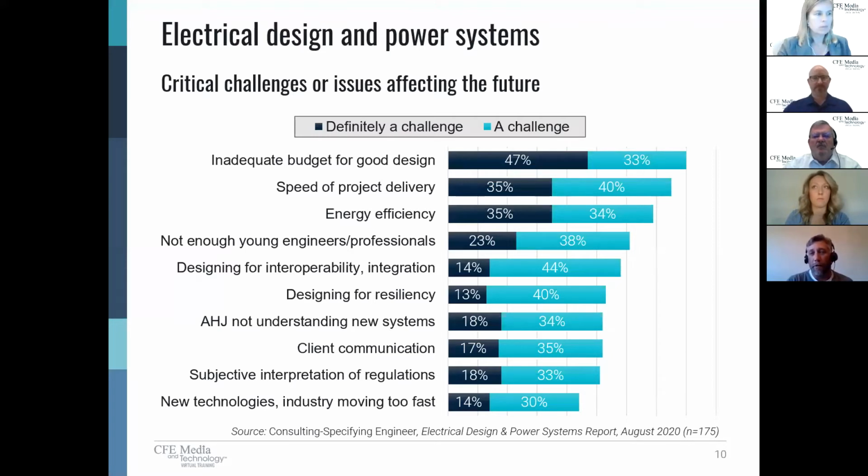In the quest of energy efficiency, clients are also relying very heavily on control systems and building management systems. Designs need to integrate and interact with these systems fluidly. Control systems, for example, do not do well with momentary loss of power. A blip that can occur in transfer of power will often crash a control system and prompt it to reboot. With buildings that have control systems, generally a UPS system that covers that BMS will prevent this and is oftentimes absolutely necessary. So that is stuff to consider within a design as well.